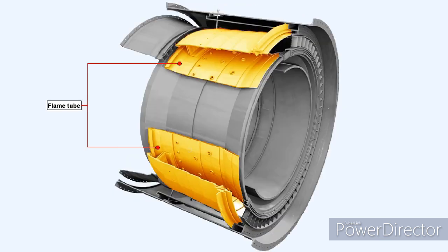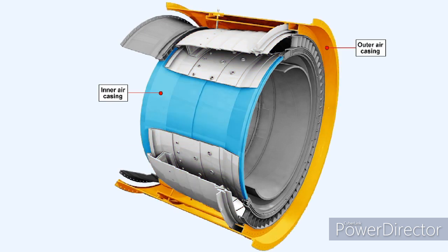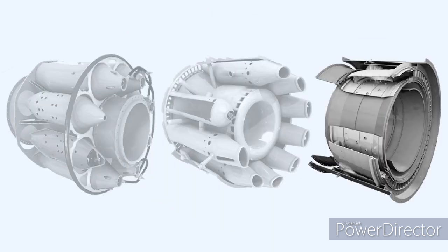This illustration is of a typical example of an annular combustion chamber system. It has only one flame tube, which is contained by an inner and outer air casing. The annular system has several advantages over the multiple combustion chamber system and the tubo-annular system from which it was developed. They are: